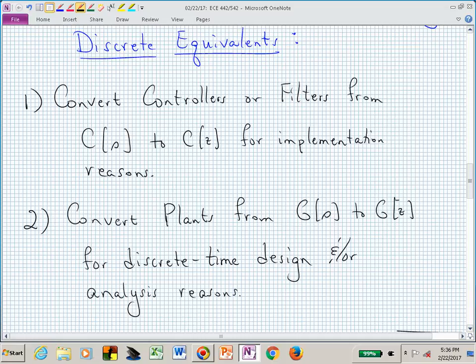And now you guys are expert programmers. That's what this symbol meant. You can now code that up into a difference equation, and if somebody now gives you a signal, a waveform, which is just a string of numbers, you can filter that string of numbers with your difference equation and generate the filtered waveform. That's scenario number one.